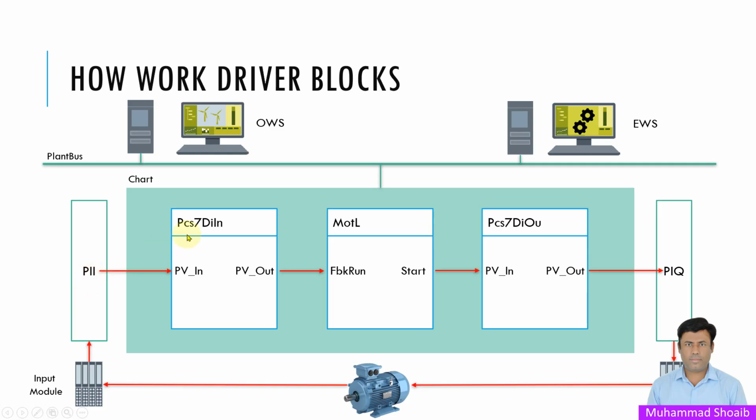Then our PCS7 DIN digital input driver block will read the signal from the PII, and then it will transfer it to our control block, the motor block.